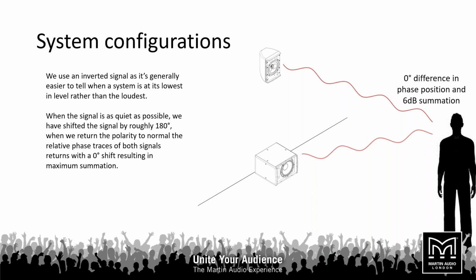Now, this is a bit of a finger in the air kind of solution to this. RTA software will definitely give you a better or more finite response. Of course, you might use the wrong wrap. You could be at 360 degrees out of phase relative, but this is a good way of getting your system at least summing in the location that you are positioned in. And of course, you can use some kind of common sense in terms of what the relative distance might be different between both these loudspeakers to give you a good idea on what delay you might need to achieve.